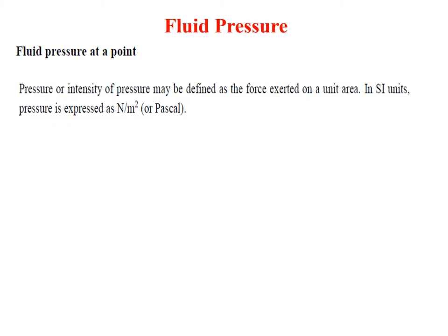So when the liquid is confined within the boundary surfaces, the pressure is exerted by the fluid at rest on the boundary surfaces, and this pressure force exerted will always be normal to the boundary surfaces.